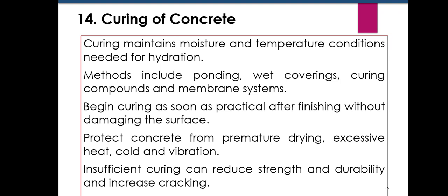So next comes curing. Curing maintains the moisture and temperature conditions required for hydration. Common methods include ponding, wet coverings, curing compounds, and membrane systems. Curing should begin as soon as practical after finishing while avoiding damage to the surface. Concrete should be protected from premature drying, excessive heat, cold, and vibration. Insufficient curing can reduce strength and durability and increase cracking.